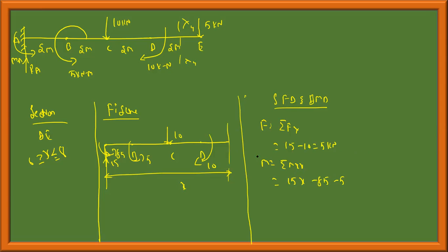If the section is bent like this, it is positive; if bent like this, it is negative. Smiley face is positive. Since the section is towards the right-hand side, this is also clockwise, therefore positive 10, positive 10.